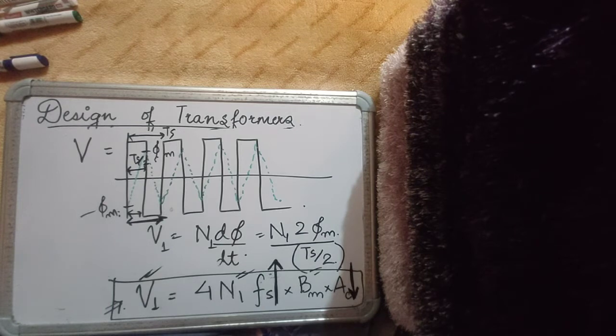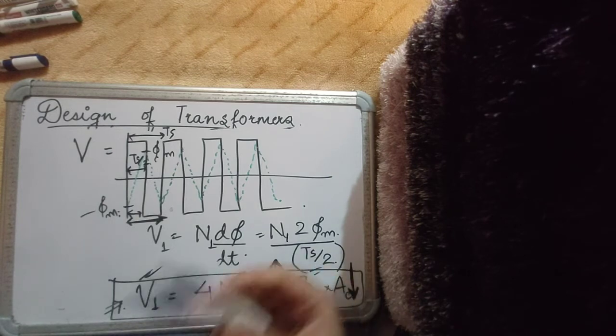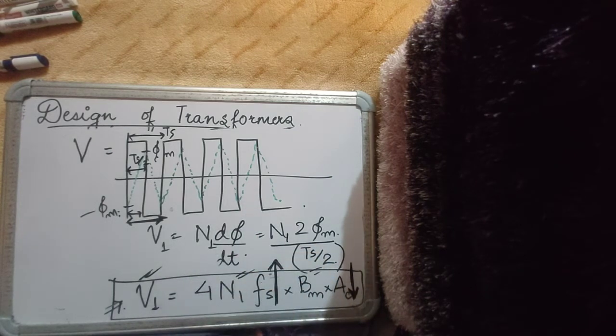So this also tells us that when dealing with transformers in power electronic circuits, we tend to use very small ferrite core transformers which have tall and narrow BH curves, and we also look for cores which have very narrow hysteresis curves, so that we are minimizing hysteresis loss, because switching frequency is high, so you're looping through that hysteresis curve again and again.